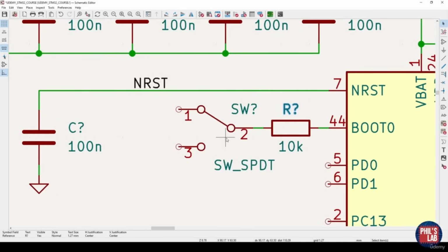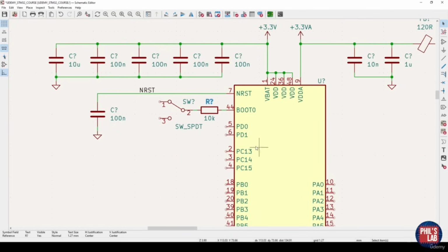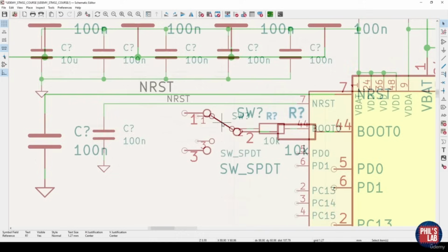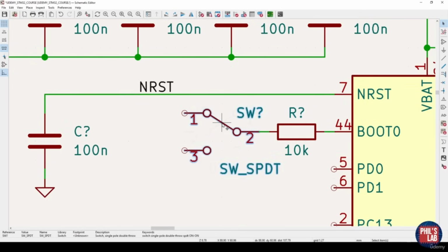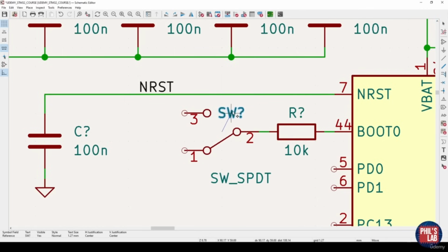So on the other side of the switch, this will then toggle between high and low. In our system, high is 3.3 volts and low is ground. You can see the default setting of the switch is by linking 1 and 2, and by default, we wish that the MCU just runs without going to bootloader mode. The way I'll do that is hover over, select, and click Y, so to make sure my default position is at the bottom. This is purely aesthetic, again rearranging.